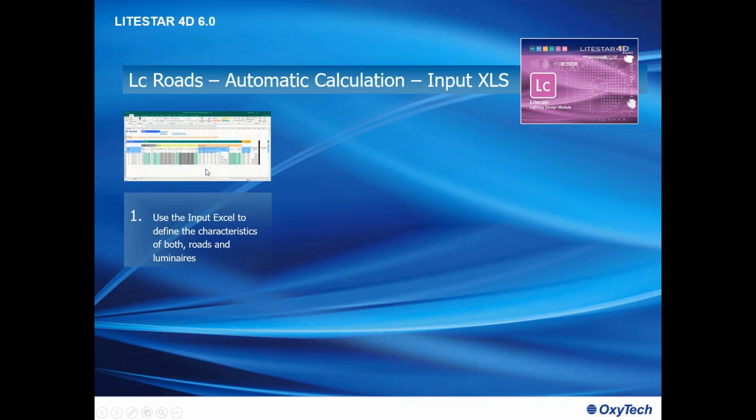So the program will calculate 7, 7.5, 8, 8.5, and 9. So 5 different configurations. And it will be the program that automatically explodes the different configurations, starting from one line and creating automatically 5 different lines corresponding to 5 different projects. This is also possible for the luminaires interdistance and for the tilting angle.